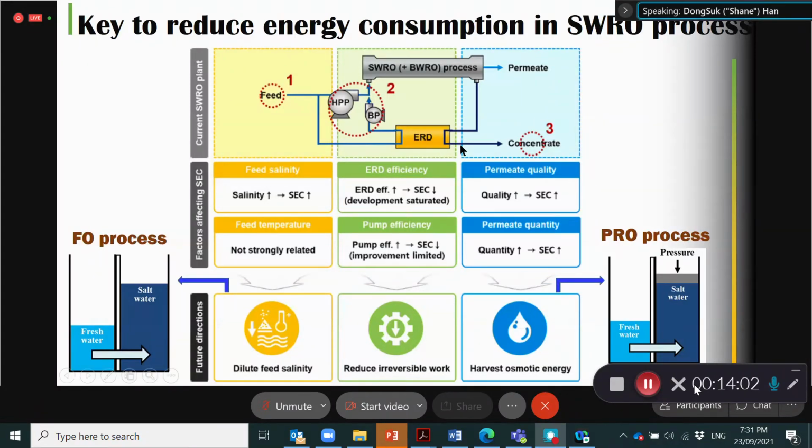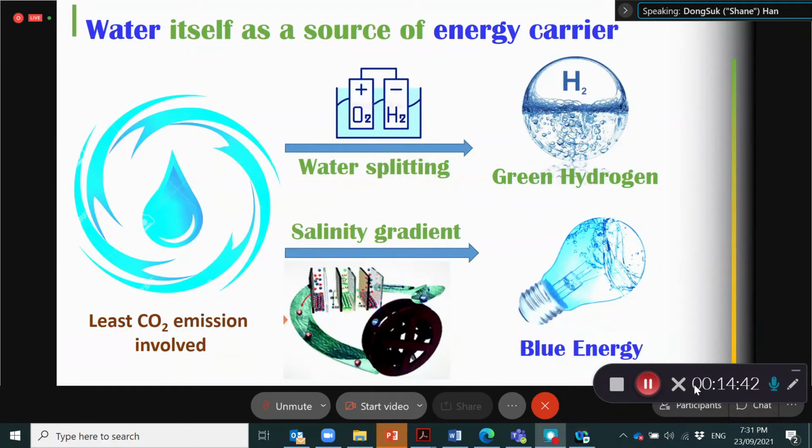Dr. Efron also explained the energy recovery device. We use this concentrate, the osmotic energy with the seawater, and the generating mechanism helps provide additional energy through the booster pump. Thirty years ago, SWRO plants consumed a lot of energy, but the invention of the energy recovery device can save more than 35% of the energy consumption in the SWRO process.